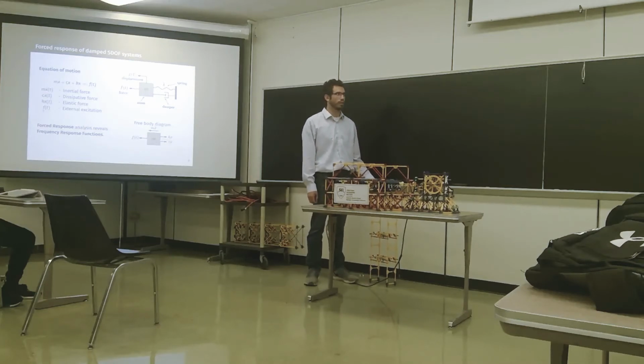So you're talking about decades of change in natural frequency. The first immediate change is, let's say a building just opened. Just before the opening, the building is empty. Just after opening, people come and move in stuff and things. There's an immediate increase in the mass of the building. That's where your sudden natural frequency change comes from.